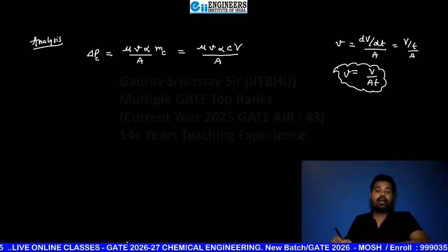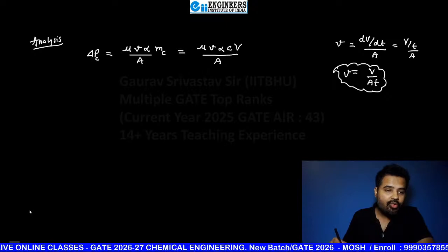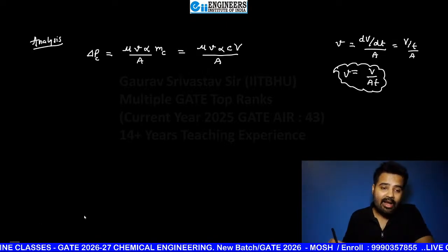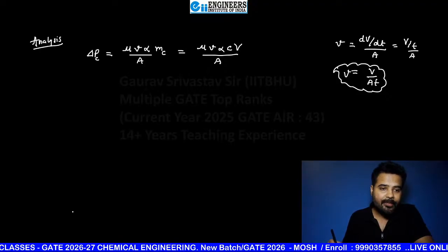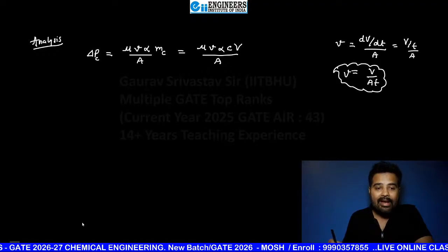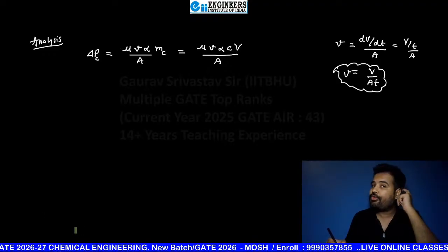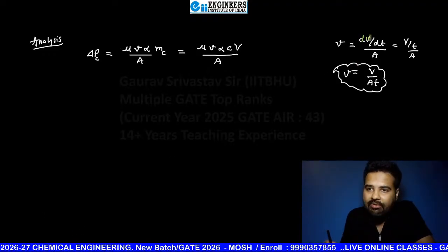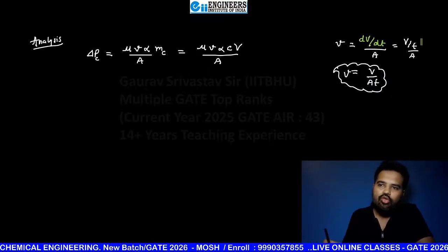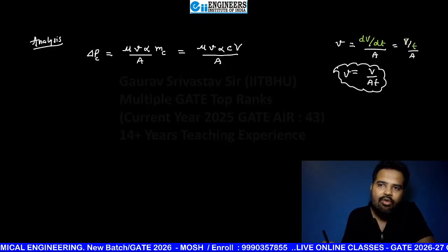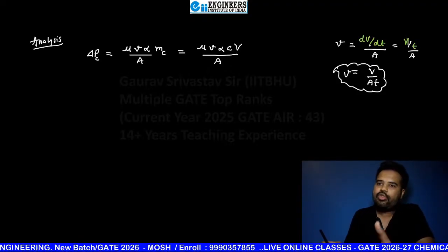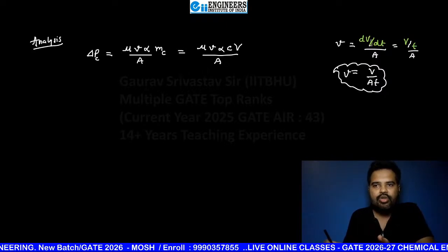Crystal clear. Okay, but I told you about this equation that you had seen before, that basic filtration equation. Now if you are dealing with that equation again, but now for constant rate filtration, that means not just dV by dt, the volumetric flow rate is a constant value. So you can write any time value, and in that time how much volume of filtrate is collected. If you are dealing from zero time, then you can write V by t instead of dV by dt here.